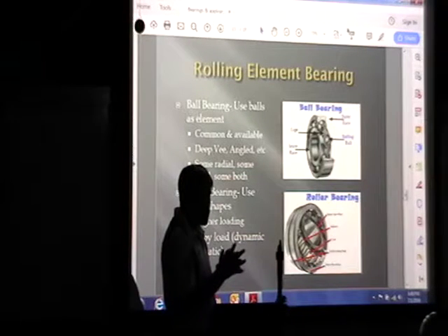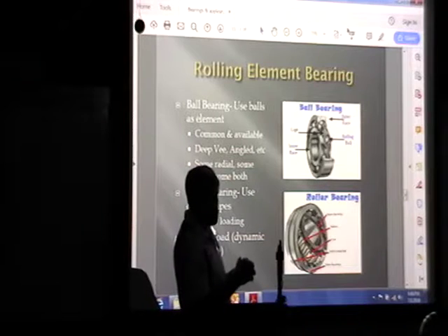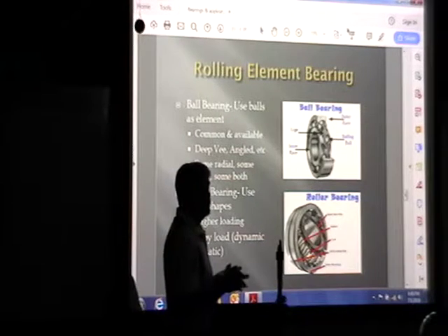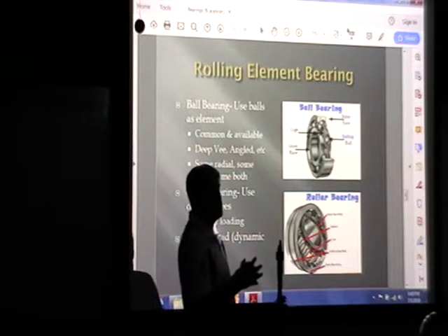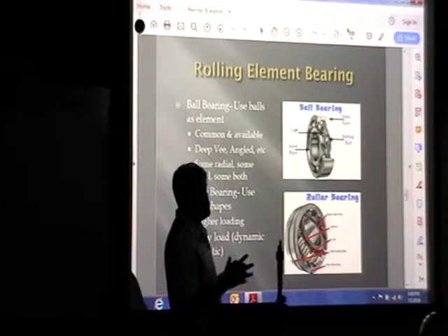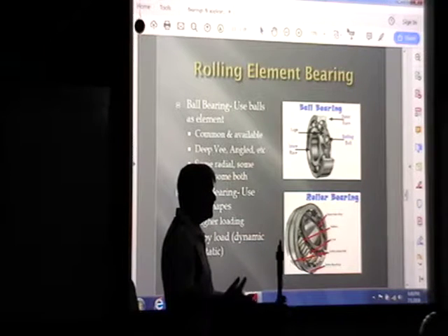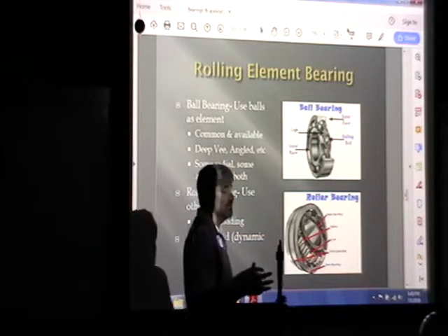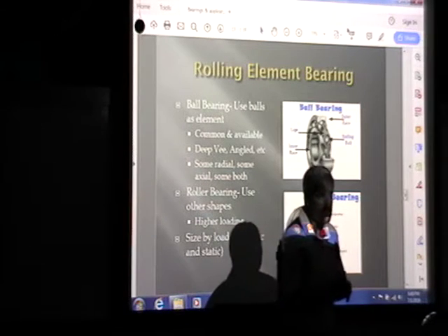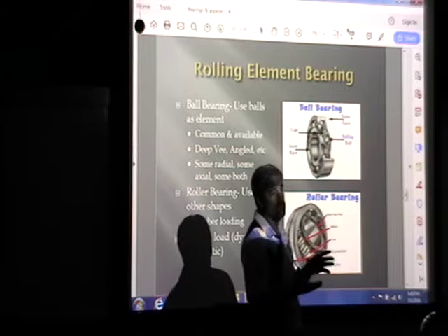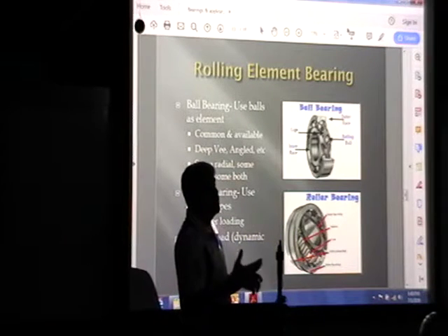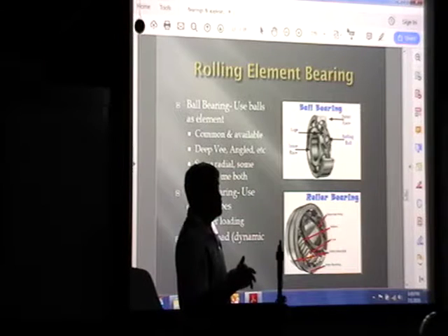Sizing these bearings, typically for a machine design application, you would look in a manufacturer's handbook, and you're going to find a load rating for that bearing in their specifications, which you'll find is a static load and a dynamic load. So the static load is any non-moving load force that bearing needs to take. For instance, in a vehicle, you're going to divide the weight of the vehicle by 4, and that will be your static load for your wheel race bearing.